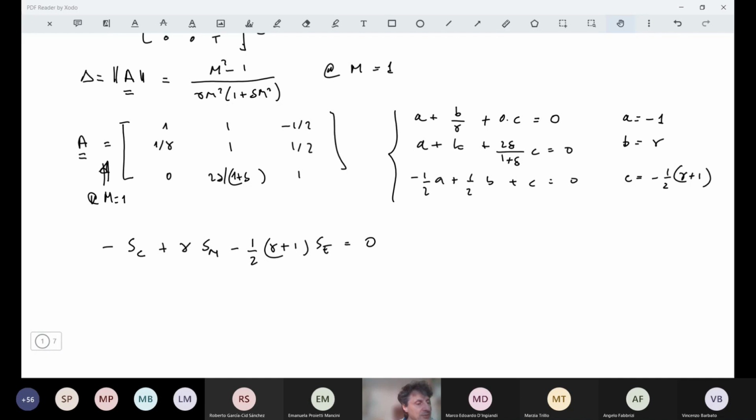So let's make now some further considerations on our system of governing equations. We have obtained expressions or dependencies of the different quantities of interest: pressure, temperature, and Mach number. We have seen expressions as a function of the Mach number and of our source terms. The same can be done also for other quantities that can be of interest. So we start from something related to P, M, and T, but for instance, we may be interested in changes of entropy. So if we recall that